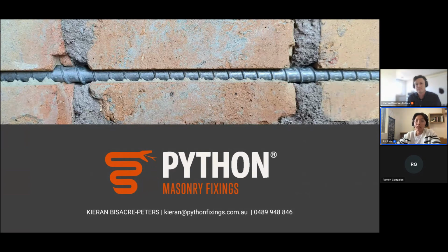If a masonry wall has bowed, will anchoring the two skins together strengthen the wall, or does it require reconstruction to reinstate vertical alignment? You could potentially prop those walls back into place and then implement some wall ties to give you the composite action that I was talking about for the increase in lateral capacity. And then potentially structurally repoint it to bring it back to its original strength. Again, it depends how far gone it is as to whether it might need to be rebuilt, reconstructed, or if strengthening is an option.